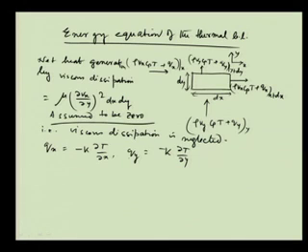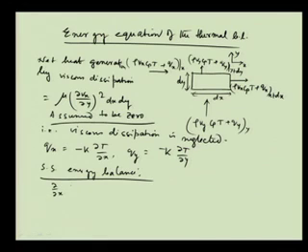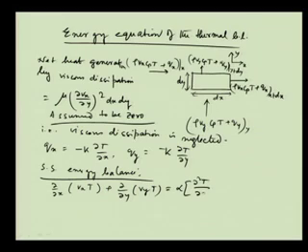So, now for the steady state energy balance in this control volume, putting all these equations together, we get del by del x of V x into t plus del by del y of V y into t is equal to alpha into del square t by del x square plus del square t by del y square, where alpha is k by rho C p, which is nothing but thermal diffusivity.